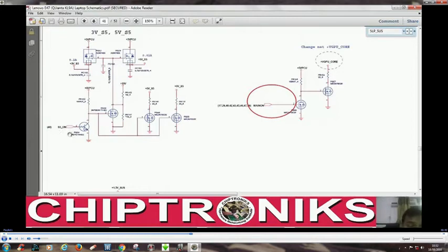When S5_ON comes, this transistor gets activated, the voltage drops here, this MOSFET turns off, 15 volt reaches over here, this MOSFET turns on, and this +3V comes over here. So after S5_ON is generated, you can get +3V_S5, and similarly 5V_S5.